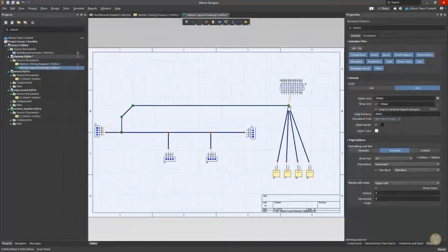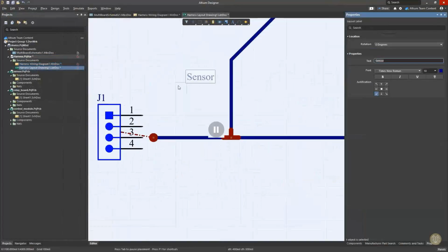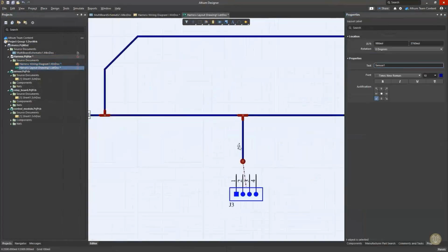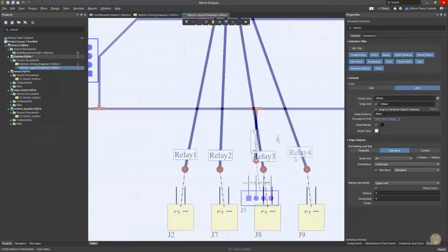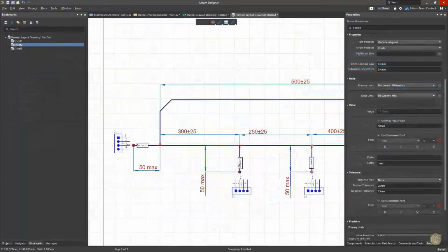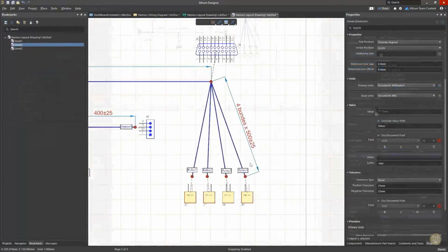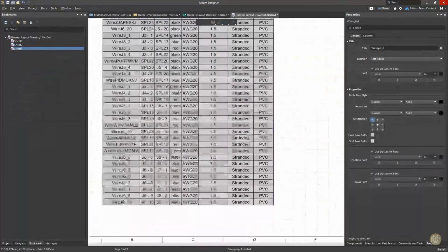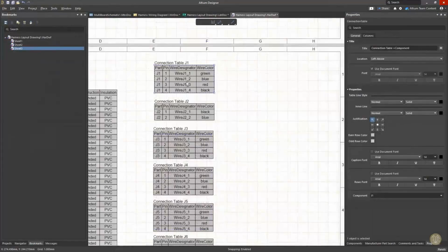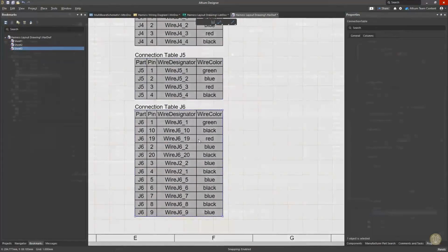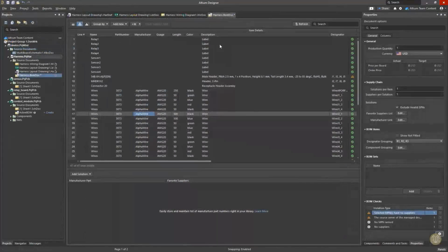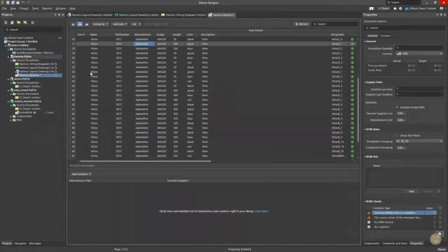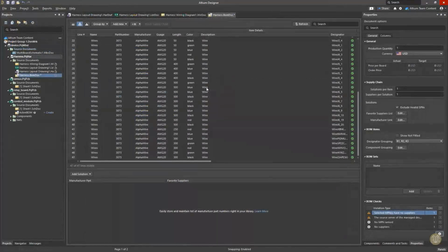In a separate document, the wires are allocated to the branches of the harness. Here, you can specify branch lengths and arrange marking elements. When everything is ready, use a draftsman document to prepare a detailed drawing and generate connection tables. All this will allow you to easily yield high-quality manufacturing results for your assemblies. And of course, the active BOM document will automatically track all the necessary items for purchase.